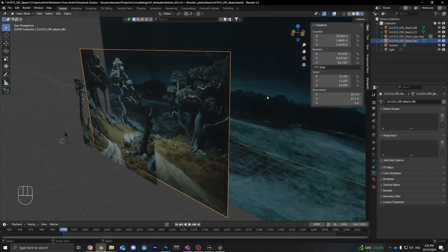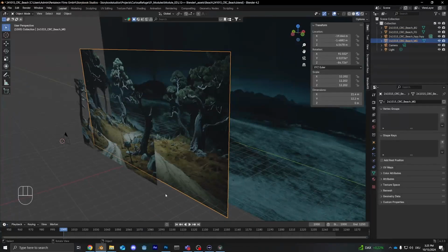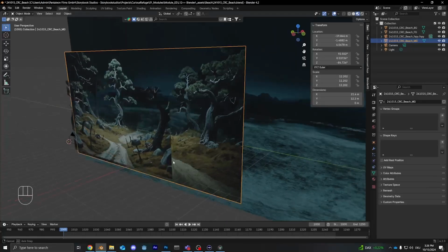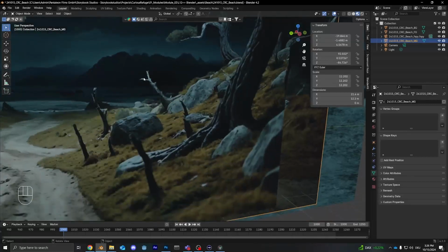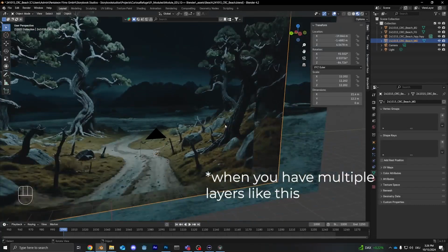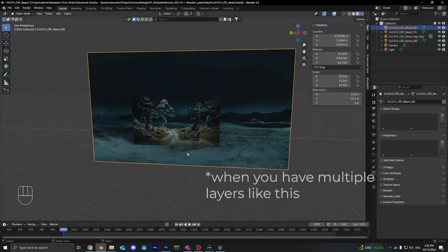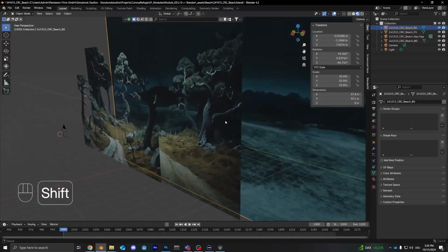One method of adding a little bit of depth to these layers is actually creating a depth map by using a ControlNet preprocessor, for example. But while I've actually done this, for example, in the backgrounds on the Storybook Studios website, I found it can be actually quite difficult to get the edges correct because they will be warped and you might be able to see kind of jagged edges. You'll see the resolution of the 3D models. Instead, for a background like this, I'm going to do something much more simple using Blender's built-in tools.